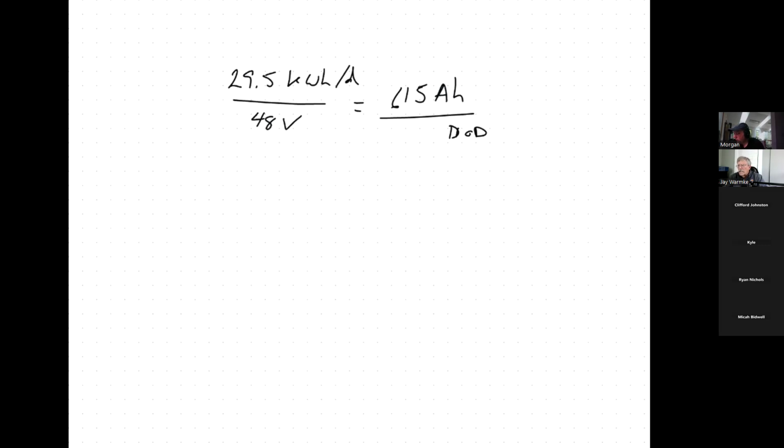And that's insolation is 1,000 watts per square meter, or irradiance is 1,000 watts per square meter. What we're doing is just taking the irradiance, which is measured in watts per square meter, and turning it into hours, which is insolation, because we need it in hours to do the equation. So I'm going off onto a tangent on that question.